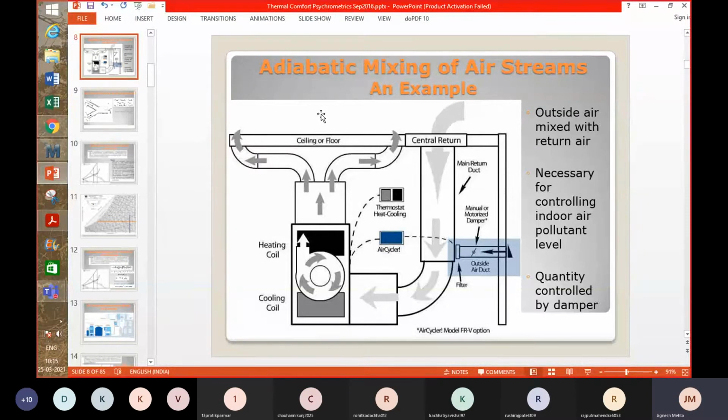And it's actually not only carbon dioxide, but there are other pollutants also coming out, and we are becoming more and more conscious about this under this pandemic situation. So there could be other pollutants or bacteria, virus, etc. Now, that should be diluted. If you don't bring the outside air, then the level of the pollutants inside the room will go on increasing.